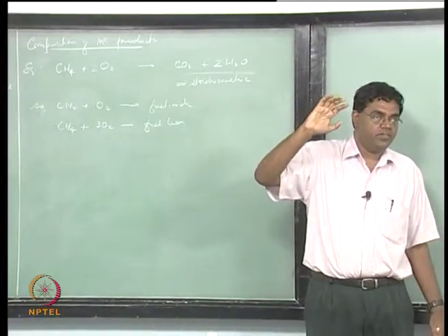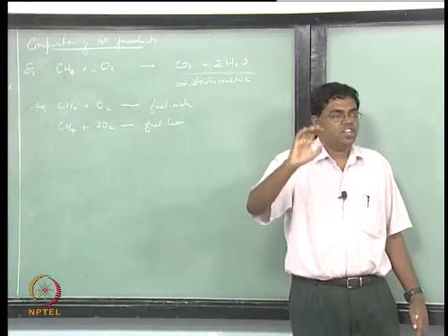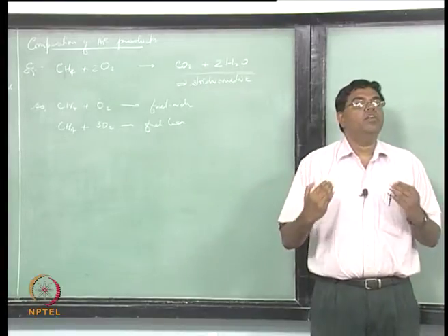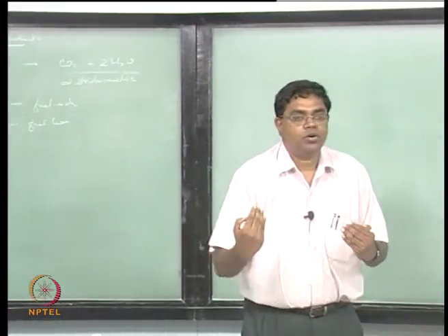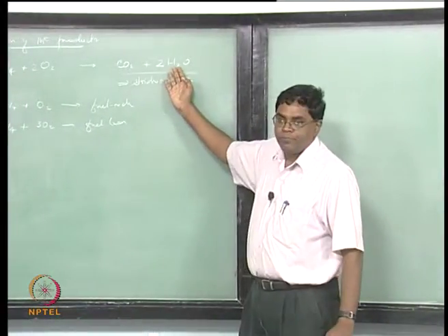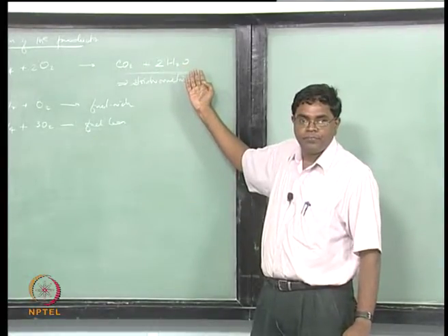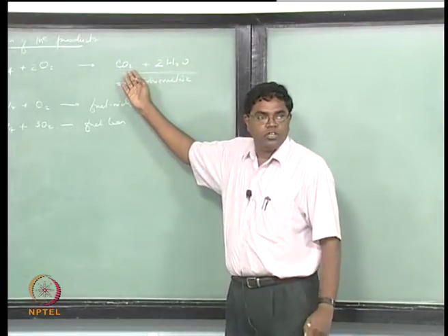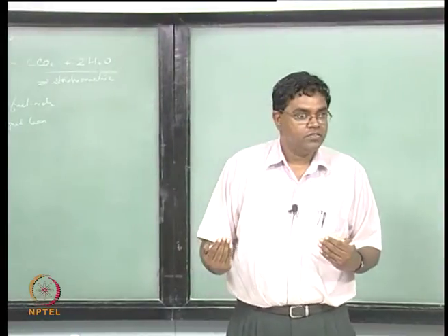You are now looking at the final state. The final state of adiabatic flame temperature is such that these products are in equilibrium with their dissociation products. So if you now have H2O, it could be in equilibrium with OH and H. So if CO2 were to decompose, it could be in equilibrium with its decomposition products.